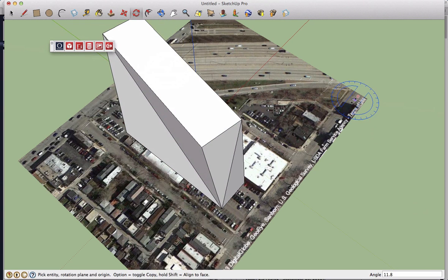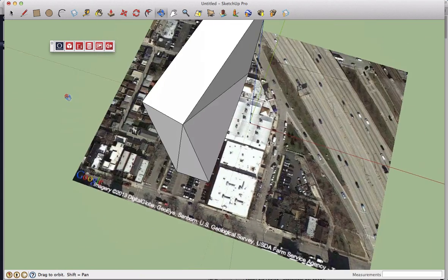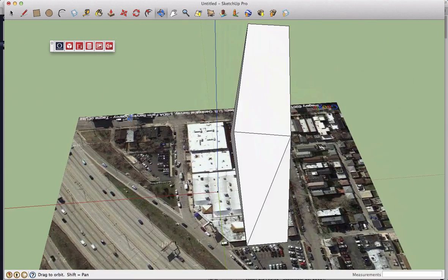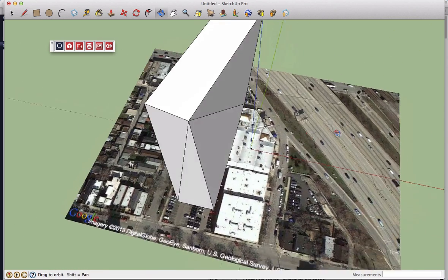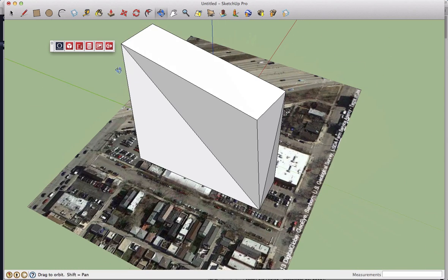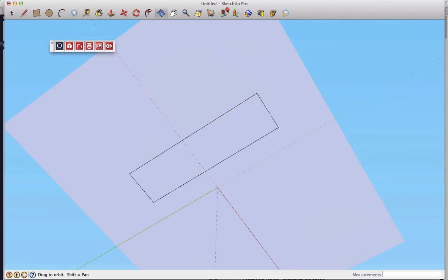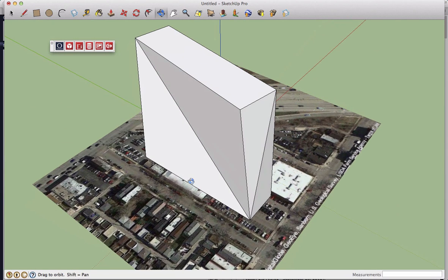The important thing in SketchUp is to make sure that the outer skin of a new building is continuous and there aren't any holes. If there are holes, like if you can imagine this being a cup that you're filling with water from the bottom, you can't have any leaks basically. So if you're cutting holes and things, you have to be careful of that.